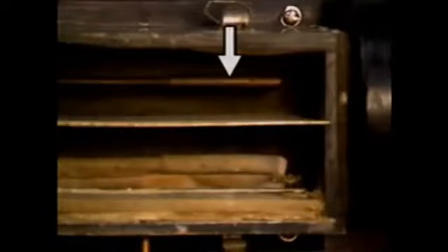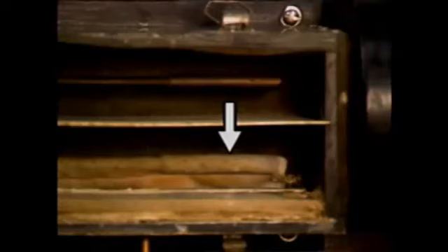Spot check humidity measurements aren't always adequate. Sometimes continuous measurements are required. When this is the case, a recording psychrometer can be used. A recording psychrometer, like the one seen here, has a dry bulb and a wet bulb with a wick. The wick is partially immersed in a reservoir of water, which keeps it soaked.